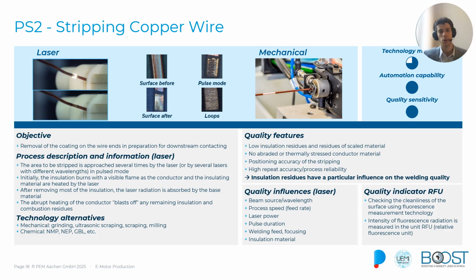It is important to have a high repeat accuracy within this process and to remove the insulation completely, because insulation residues have a particular influence on the welding quality.